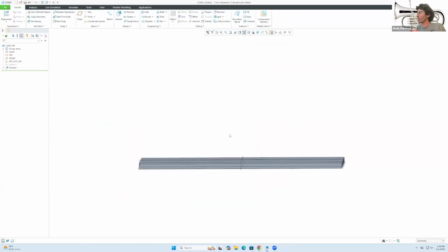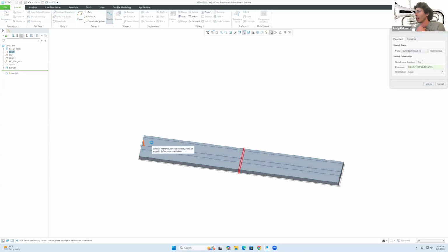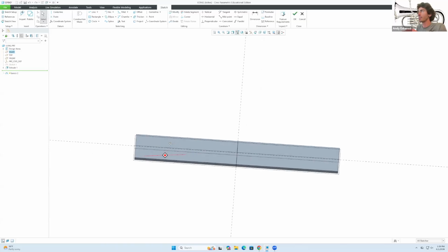So we got the first one of these rectangles that we have in here from our gong design. Let's add 3 more. So how could you do that? Well, I'm going to go back to Sketch, go to that face, and click on Sketch. So now we're going to be drawing in there. And now, yes, I'm going to use one of the commands that I wanted to use just a second ago with the xylophone, which is this one that's called offset entities. So if I click, for instance, on that line, well, let me just change. If I only click on one line, essentially it's just creating the same line exactly like it, but at an offset of 20.